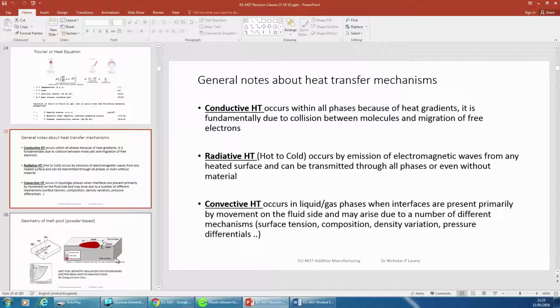There's obviously conduction and very high cooling rates going on. So when you have actually melted the powder and that starts to solidify, you've got a thick base plate underneath which draws away the heat very quickly, so you've got high cooling rates. Those high cooling rates give you very different microstructures in the materials than you might have from casting or from other slower cooling processes, like hot isostatic pressing or hot pressing.